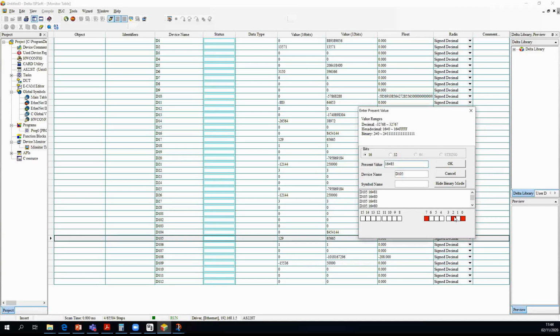So if I enable this bit, then when I trigger a new position command, you should see that it is not happening because I have not sent the drive to the home position, because I've not done a homing on this drive. So it's very important to keep in mind that if you want to do absolute positioning, then first you need to do a homing procedure.